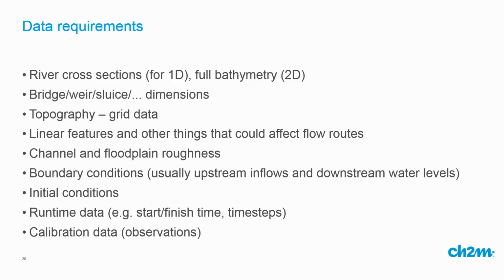To drive these models you need water coming in, and that's the boundary conditions, the water coming into the model. Usually the boundary conditions are an upstream inflow of water and a downstream water level or downstream rating curve. If you've got a tidal situation, you need to capture that tide curve and any surge on it as the downstream boundary probably, and that would then push water up the channel.